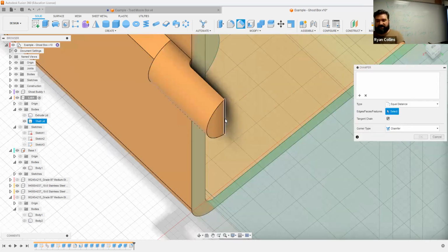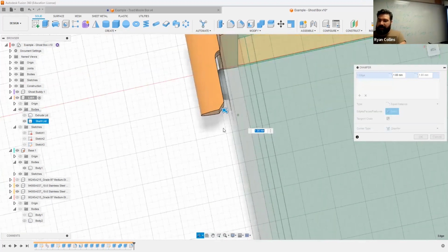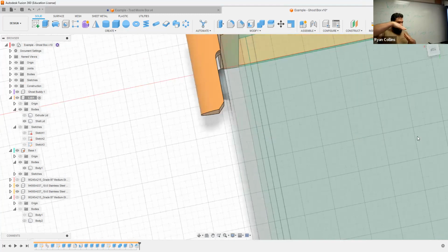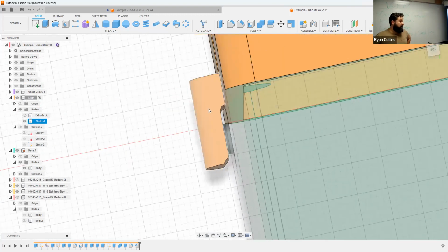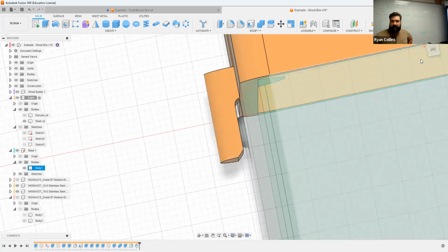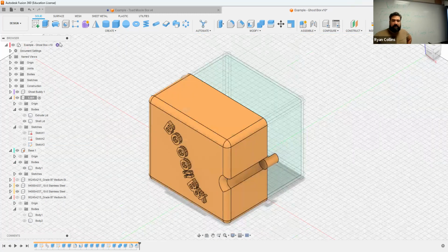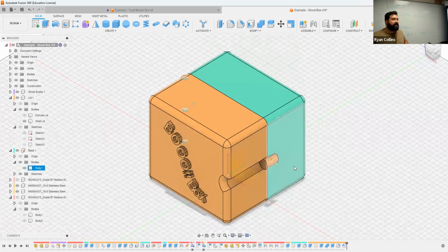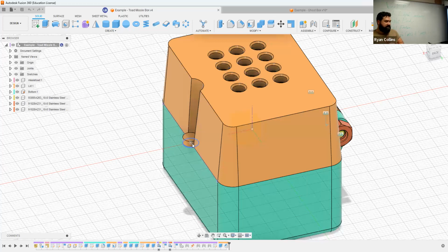So I'm going to select there, just that base, that little edge, and I'm just chopping that in a little bit. Not so much that it actually takes a chunk away, but the reason I'm doing that is it adds a little ramp for that bump to leap off of. So it's kind of a funky little thing. I wasn't planning on making this based around a rounded object, but I like that little thumb tab feature. So that's a simple way to create a really simple little latch versus just this little thumb point that gives you something to grab onto.